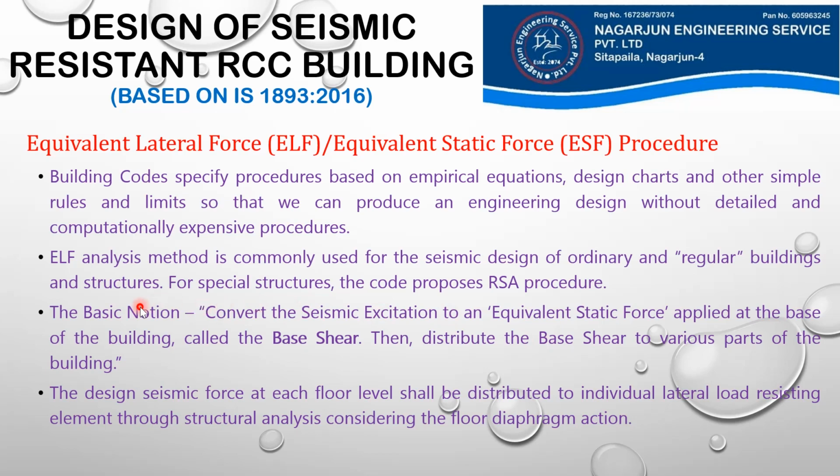Just remember this, the basic notion is to convert a dynamic vibration. This seismic excitation is a dynamic loading. We convert that into an equivalent static force and apply it at the base of the building. And we distribute that base shear to different levels or different stories or different parts of the building, and that design seismic force at each level shall be distributed to individual lateral load resisting elements through structural analysis considering the floor diaphragm action.